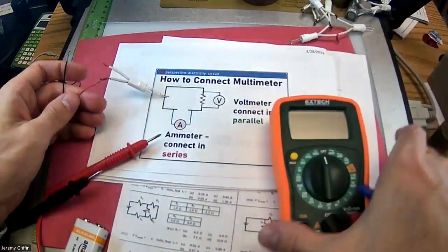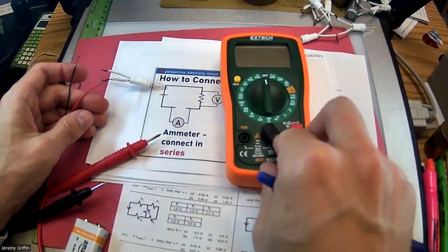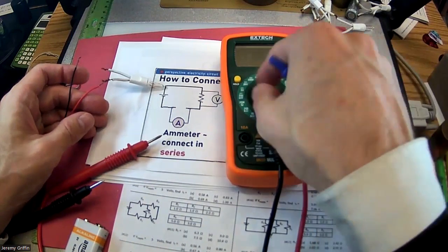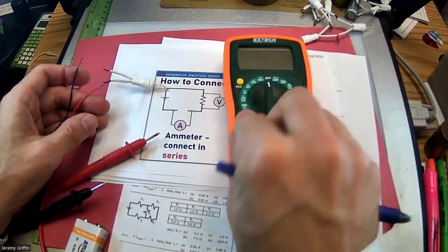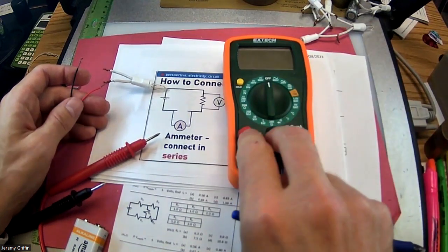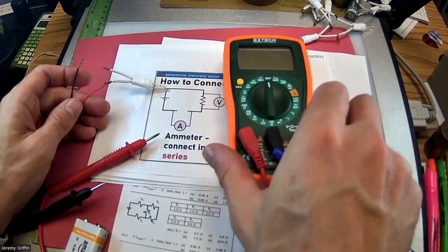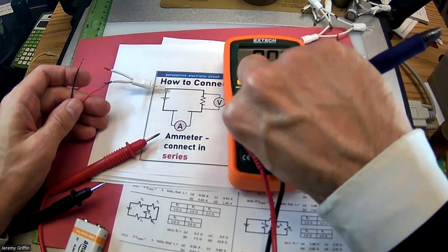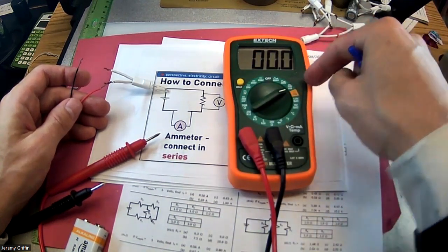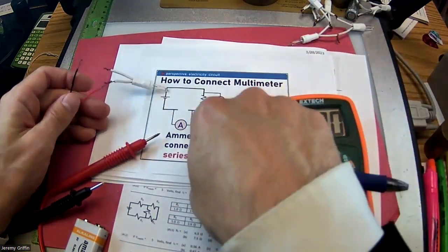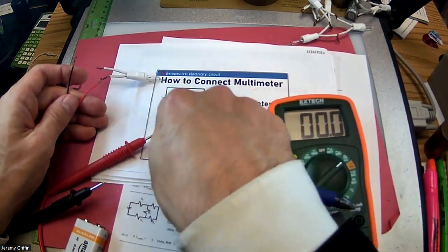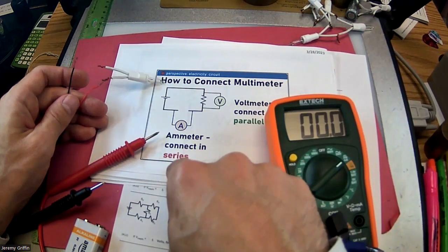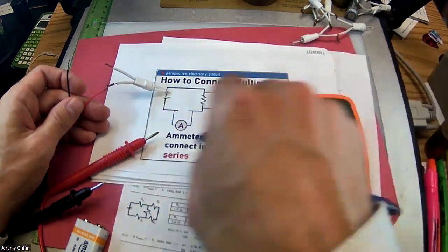Okay. Let me start with amps. So this is a multimeter, so it can measure different things, different functions. I'm going to take this guy, pop it out over here, leave one in COM, giving you guys a really fast crash course here. So show you guys how this works. Flip this one over to measure amps, and now amps is measuring current. So you have to break open your circuit and connect the ammeter function in series with your circuit and force it to flow through the multimeter.